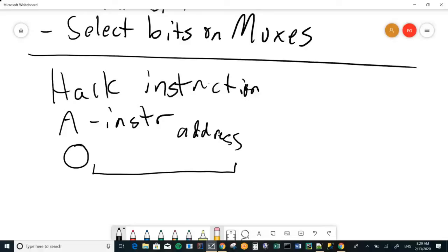If we decide that a particular architecture is going to have an A instruction and a C instruction, why is that the case? We made it up. Why is it that the signal for an A instruction requires a 0 in bit 15? Because we made it up. We just invented it. We could have flipped it around. We could say there has to be a 1 here and then a 0 for a C instruction. We could say bit 7 in the middle is what distinguishes an A instruction and a C instruction. You can build a CPU that way and it'll work.